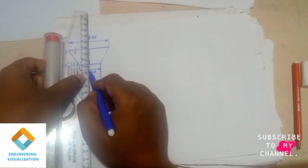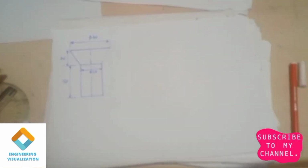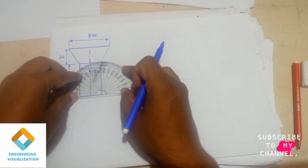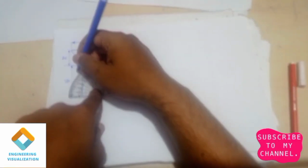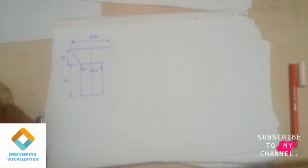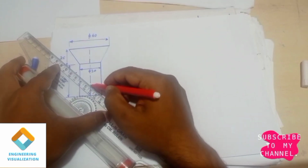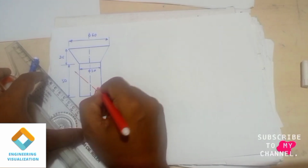So we need to draw an angle line, and that should be at an angle of 45 degrees. Take the protractor and mark at one of the corner ends. Yes, we should mark one of the corner ends. So mark an angle of 45 degrees. Now draw a section line cutting it, and to show the section line I'll be using a different sketch pen, a line-dot-line. So it is exactly cutting at an angle of 45 degrees.